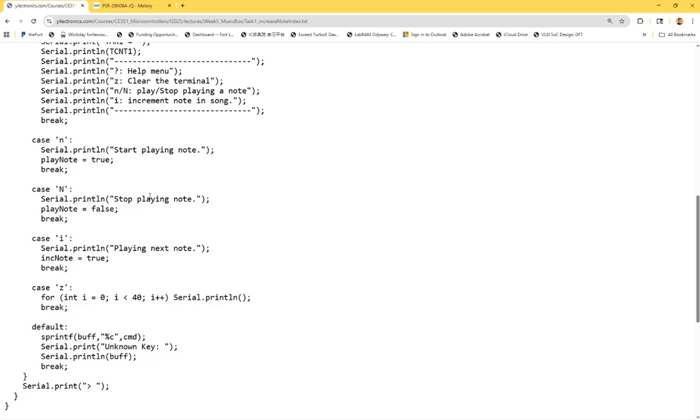So timer counter 1 overflow interrupt, which means whenever it finishes all the counts and overflows, it interrupts. So slightly different from the one we did in tutorial 2, because in tutorial 2 we don't really call a function after it overflows. We're just looking at the flag, right?